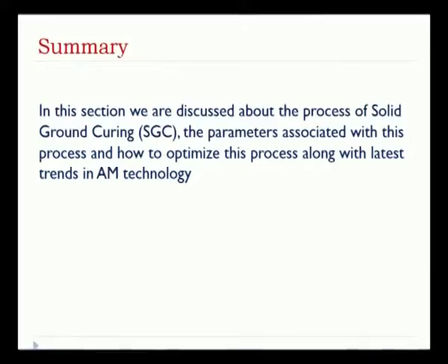Okay, in this session we have discussed how the solid ground curing process is accomplished, followed by what the parameters in it are, how effective the parameters are, and finally how the process is being optimized, right? Finally, at this last stage, we have seen some of the latest trends in AM, particularly the trend related to the SLA process, one of the effective curing methods for component buildup.